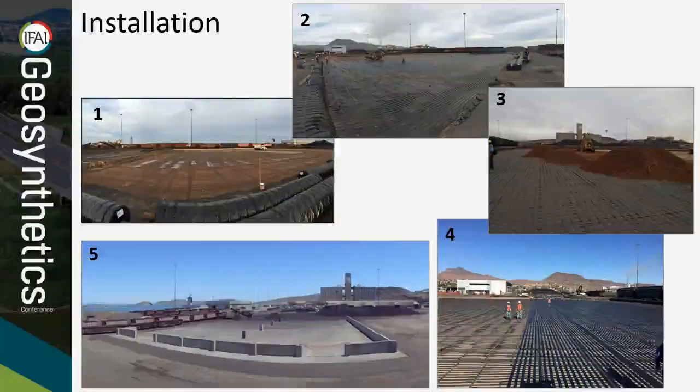At both edges of the geogrid, an anchorage length of 6.5 feet was left out to eventually wrap around the geogrid. Picture number 3, we see the installation of the second layer of high-strength geogrid and the placement of fill material. The fill material was placed in lifts, paying a lot of attention during the spreading and compacting phases. It has to be spread and compacted in the longitudinal direction of the top high-strength geogrid.